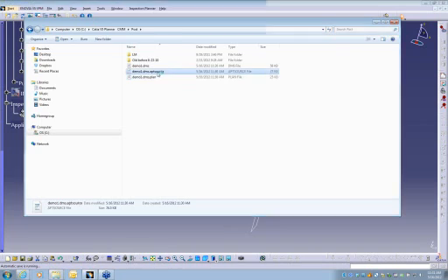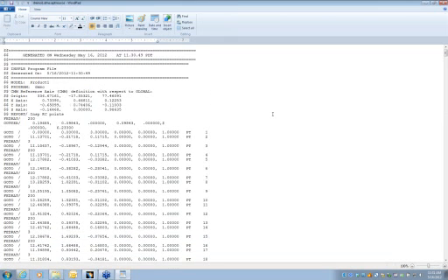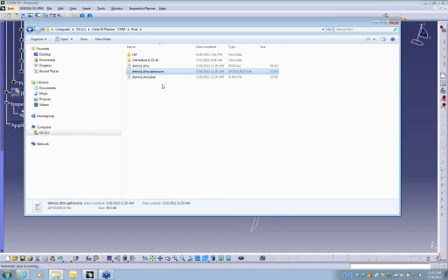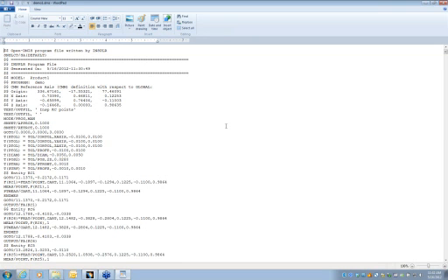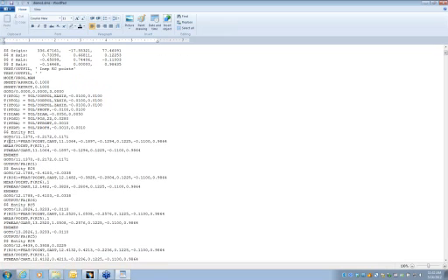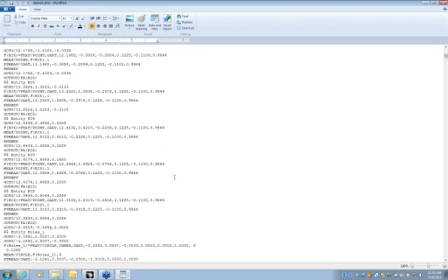The other thing that we created is an APT source file. This file is ready to put in any CATIA NC process or into third-party simulation that uses APT source, like Vericut. So this basically simulates the exact code that the DMIS is going to follow for holes and everything. And then what you're going to run on your CMM is this file right here. This is your DMIS file. So this is your tolerance information, the output statement, and your point measurements with the key names in it. So when we go to measure those points, the output will follow those names.